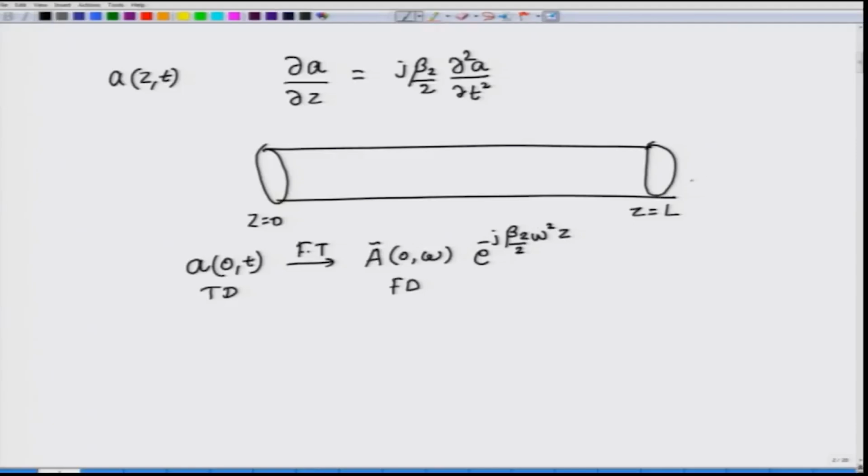but it turns out that numerically when you are solving these equations, otherwise the numerical solutions will become unstable. To avoid that numerical instability, what you do is you section up this fiber into small sections of some delta z long. It is not required that you section them up into equal parts, but it is usually easier to code that way when you do it with equal parts.